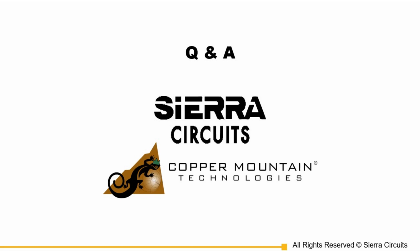Secondly, one thing which is very important, if you try to do port extension over a wide frequency range, it simply won't work, because anything you look through is going to have some dispersion, and port extension assumes a constant delay. You're just dialing out one delay, and if the delay is not constant, your results will be terrible. And you'll see that when you try to do the port extension, instead of getting a dot on the right-hand side or wherever you're aiming, you're going to get an arc or a bunch of squigglies.